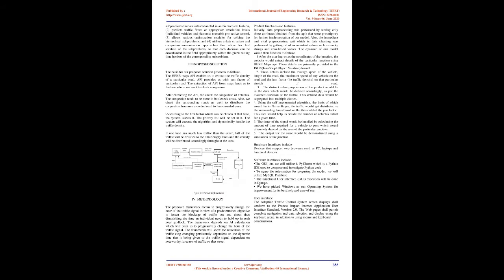The core of the idea lies in image processing of the already existing traffic API provided by Google. Google Traffic API provides the real-time data of the traffic conditions for any given coordinates, which gives color-coded traffic density data, which can be further processed to analyze the traffic flow at a given traffic junction, and hence, the traffic lights can be dynamically controlled to regulate the traffic. This system works to make sure that there is not an uneven distribution of wait time and therefore uneven accumulation of traffic at a junction.